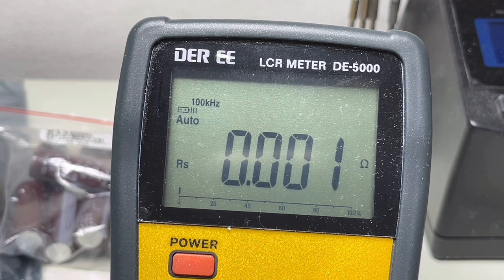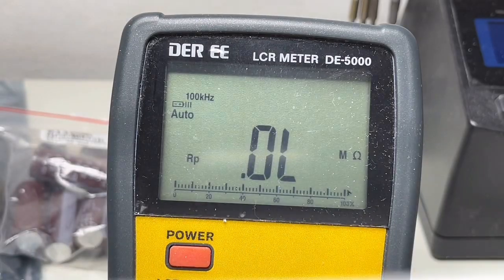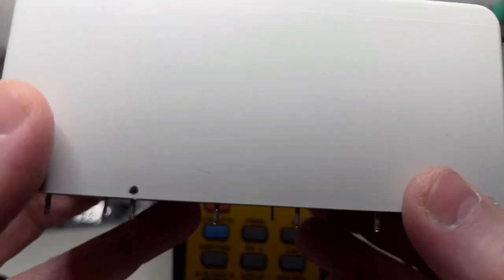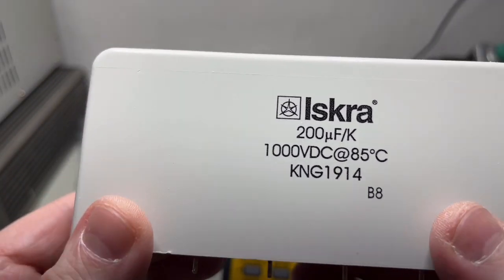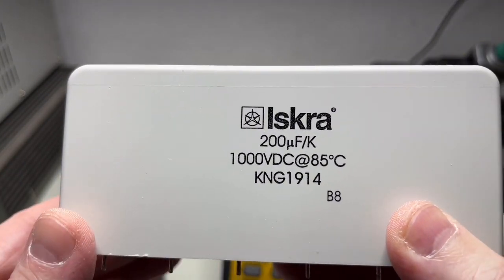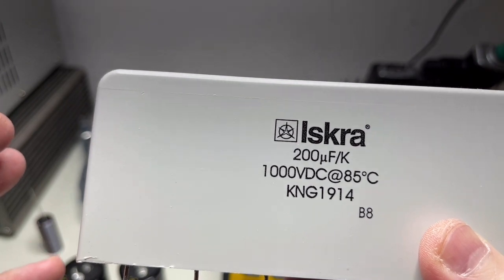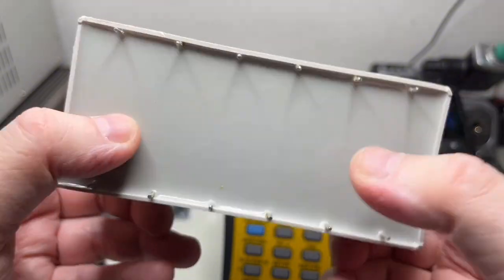There we have the 1 ohm, but I don't know where they stated 10 kilohertz. Anyway, you see the ridiculous low ESR of this capacitor. 1 milliohm. Guys, a sense resistor is even higher than that with milliohms. If you use a 5-watt sense resistor for, I don't know, a few milliohms to measure a lot of current, this has more resistance than this one at 100 kilohertz. Deadly bad boy.